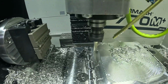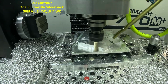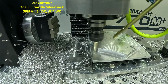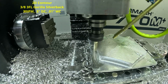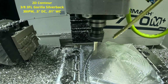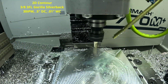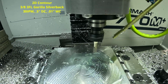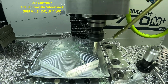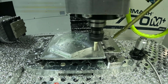And now we will start to transition into a 2D contour. So we're finishing our sidewalls. Same 3/8 3-flute Gorilla Silverback end mill, 30 inches per minute, half an inch depth of cut, and 10 thou for our width of cut. So we're really just cleaning up the 10 thou we left on our walls to get a nice surface finish. So we'll continue with this toolpath, and then we'll get into the 3D pocket, which is really where most of the machining occurs.